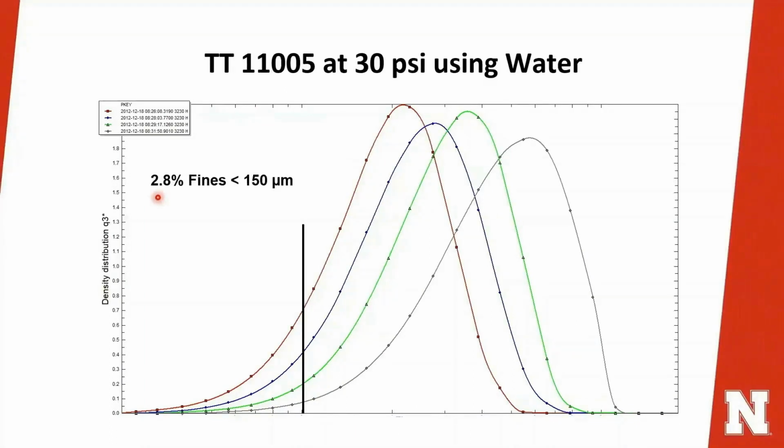Now this is what happens when we change the nozzle design. Instead of using an XR nozzle, we are using the TT nozzle here. Those nozzles were very popular when glyphosate was released because they do a better job of mitigating drift. So take a look, now we are down to 3% of fines, just by changing the nozzle here, guys. And we can still do a better job.